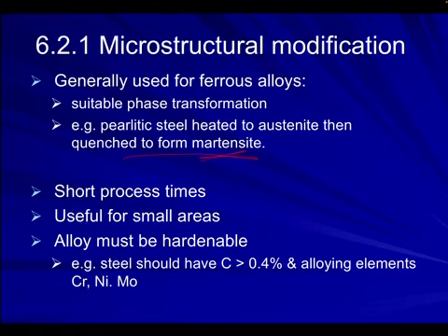Alloy must be hardenable, so you have to have a steel of maybe more than 0.4% carbon, plus alloying elements like chromium, nickel, and molybdenum are very useful.